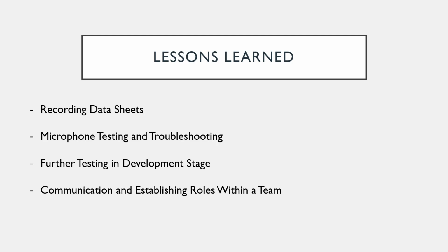We learned a lot of valuable lessons. One of the big ones is very closely reading the data sheet. The data sheet for the microphone that we ordered actually had a small circuit that we didn't notice. And we also noticed that our input voltage that we put into the microphone was too large, and if we read the data sheet better, we wouldn't have had this problem.